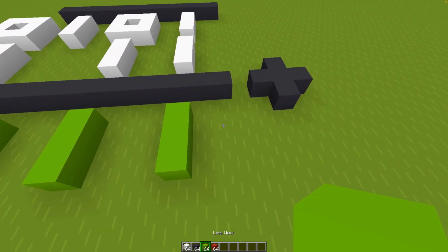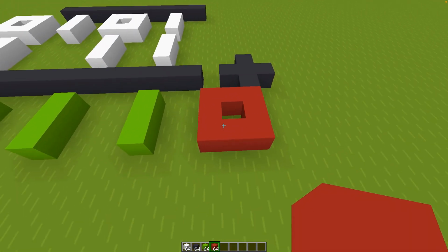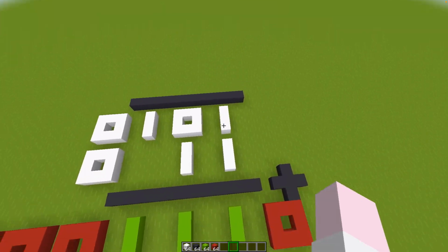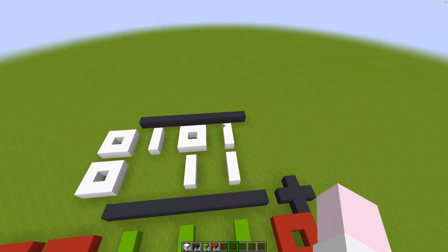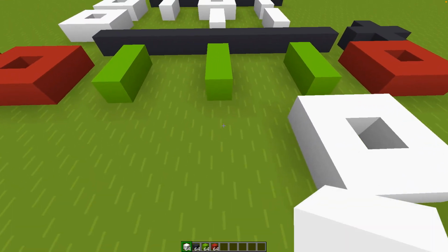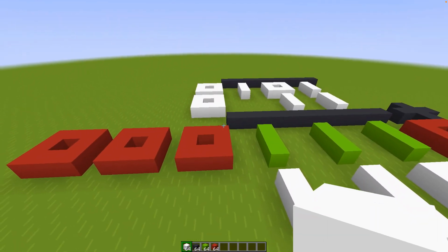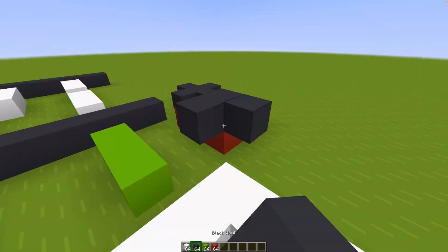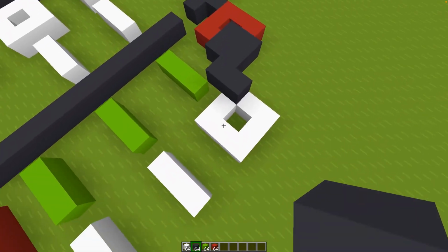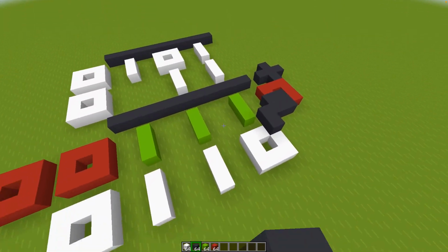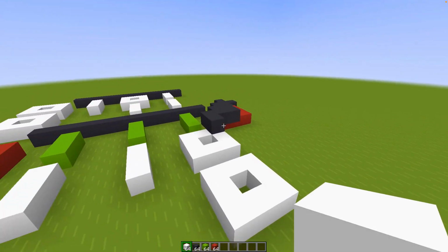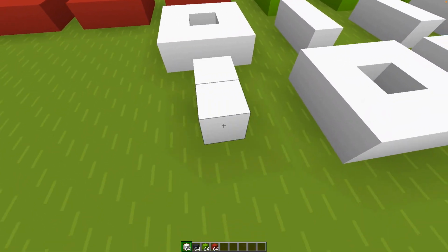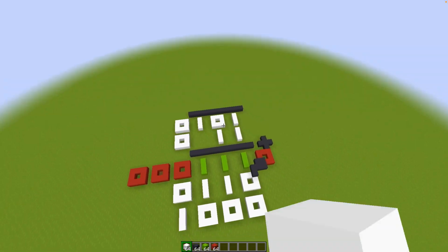and that's what the carry line looks like now. Now what we're going to be doing is add our carry in bit, which is just going to be a 0 for addition. And now we want to XOR every one of these digits like so. So 1 and 1 is going to be a 0, then 0 and 1 is a 1 and a 0 is just a 1, and that's going to be a 0. There we go. Now what we want to do is we want to XOR the carry line diagonally. So this one is going to XOR this one is going to XOR that one. So our result will be 0 and 1 XORed is a 0, again a 0, and now 0 XOR 1 is a 1. So our result is going to be 8, and 5 plus 3 is indeed 8.